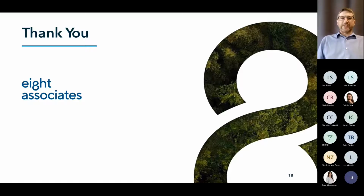So now we're starting to see different requirements out there saying you should include sequestered carbon, or you shouldn't include it, or you should include it at one stage but not another, and it's getting a bit complicated. But effectively, over a whole life, if it's included at the early stages, then it has to be included as a disbenefit at the end. Or if it's reported only at the beginning, at the upfront stage, then that's fine, but it needs to be declared whether or not biogenic carbon is included in the results, or it could be reported separately.